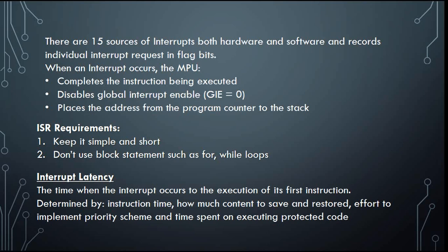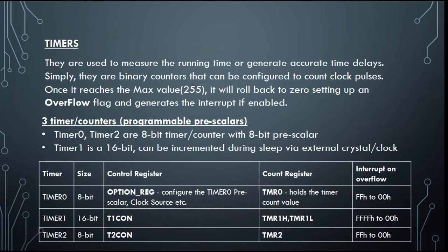So the ISR requirements are that you should keep it simple and short and do not use block statements such as the for and the while loops. Timers are also peripheral devices.